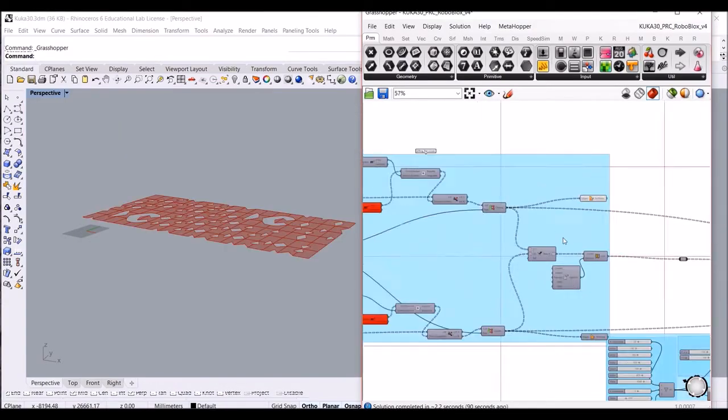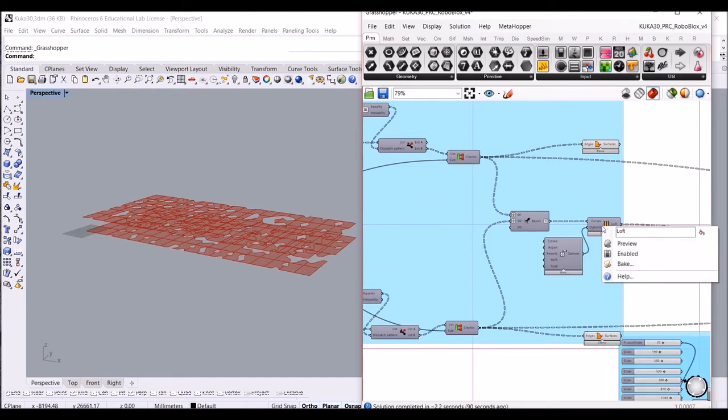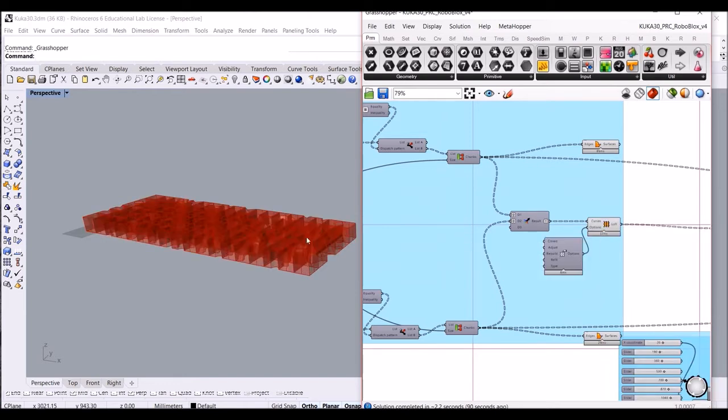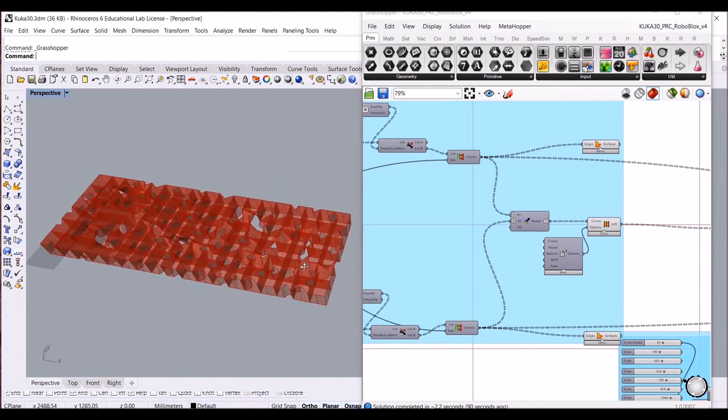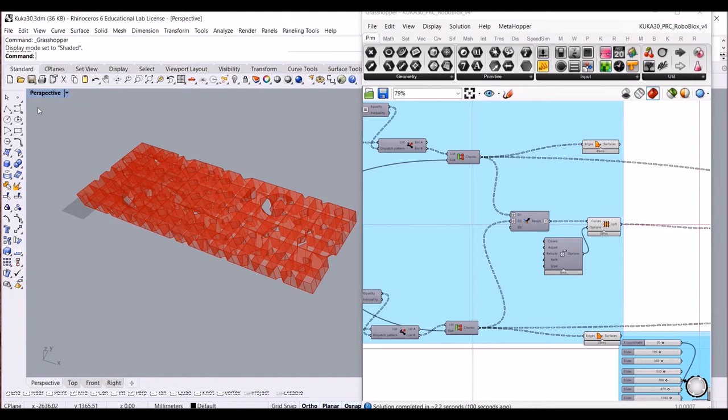In our Grasshopper program, we take the curves defined in the web interface as the front side of a panel and the back side of a panel, and then create a loft in between these two elements, which creates the in-between lofts of the two curves.